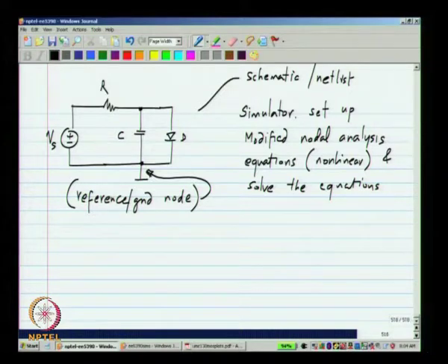And finally, let us say in this very simple circuit where there is only one variable to be solved for, V1, I will quickly write down the expressions. The current through the diode plus the current through the capacitor plus the current through the resistor has to equate to 0 by Kirchhoff's current law, and these currents are a function of V1.